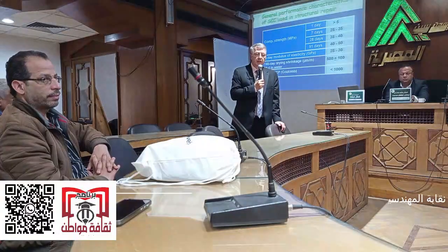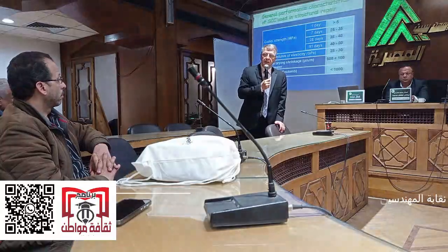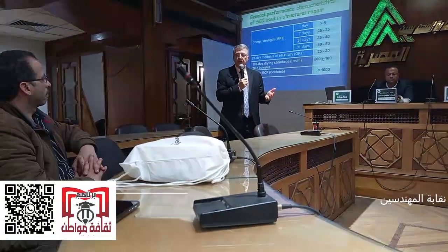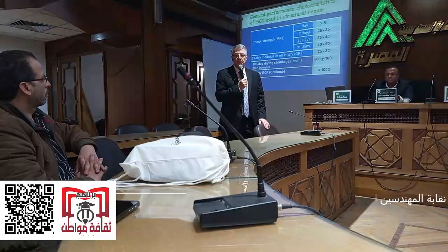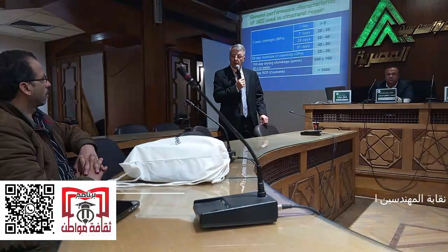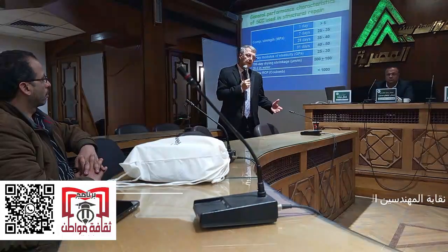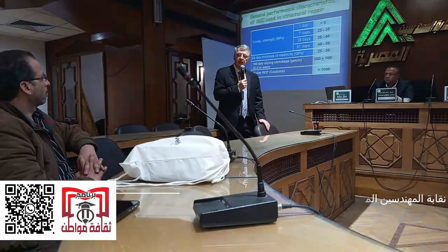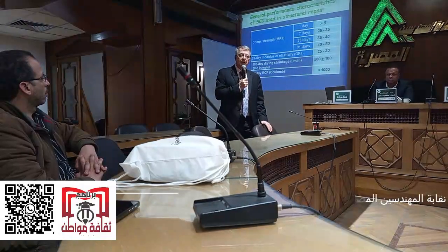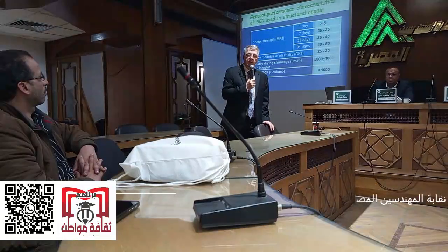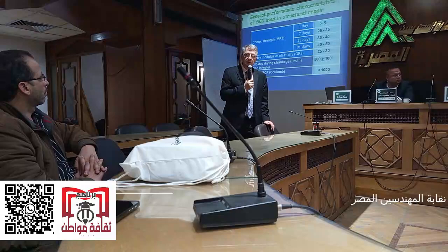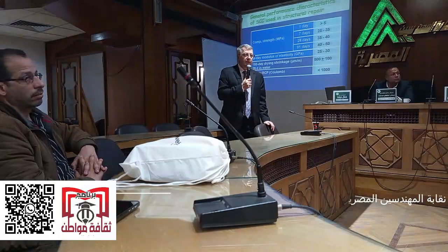But you can make 80, 90 megapascal concrete that is SCC, and it's been made. You just have a lower water binder ratio. You put in fly ash also. Yes, 5%. I'm not going to tell you 5% or 25%; you have to work with the materials. Burj Khalifa, for example, is a C60 concrete. The Kingdom Tower in Jeddah is C90 concrete. By the way, it's all SCC.